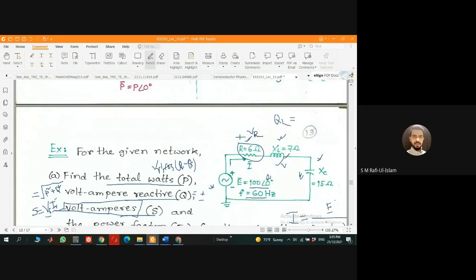Since it's a series circuit, there are many ways of solving it. Can we write it like this: I modulus squared, meaning magnitude, times ZL, which is also a magnitude? Can you calculate this? Probably we can, right? Yes, sir. Just the XL is enough. Or even we can calculate the voltage across XL, and then use the formula V squared divided by XL.